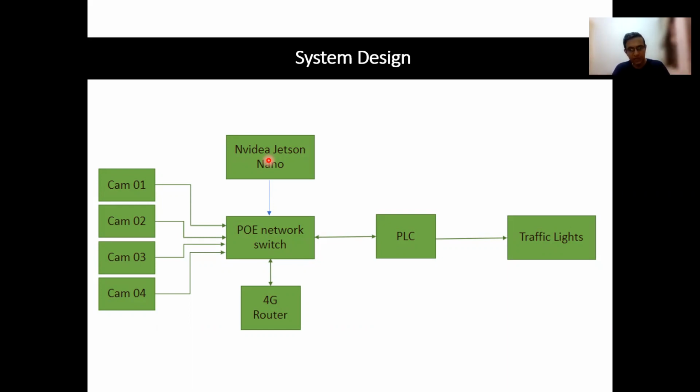Altogether it is 150 seconds, and the next cycle is also 150 seconds. So you're not going to change the 150, but you're going to take a few seconds from this phase and put them into the other phase. This is an internal adjustment, but we keep the 150 seconds intact.